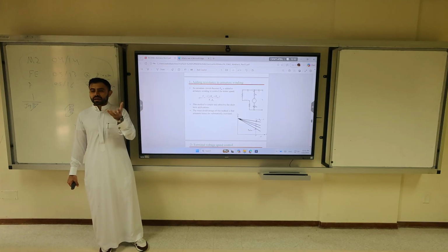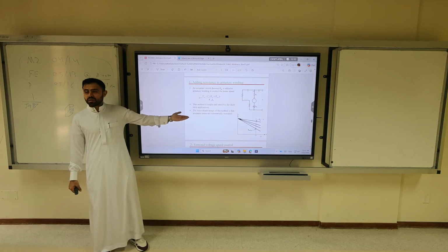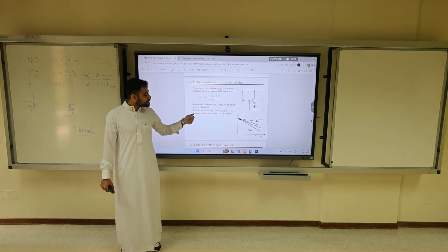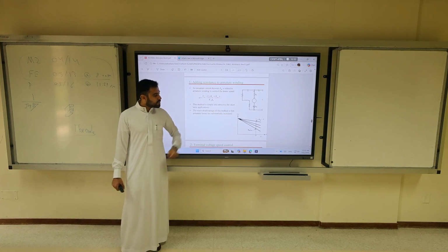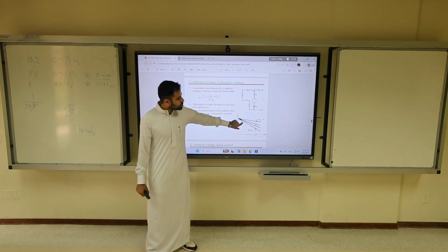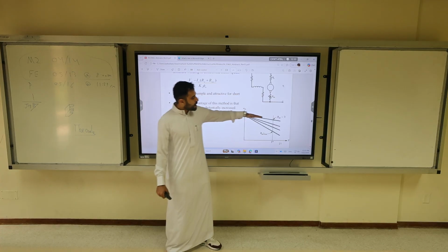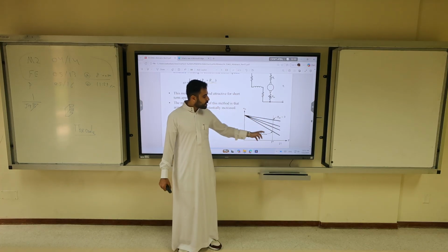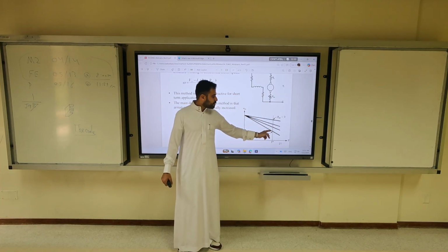What is the drawback? This is one of the questions that I like to ask in the exam. The main disadvantage of this method is armature losses are substantially increased. So this is the curve. RA at 0 is that. If you keep increasing it, you might reach a point where the speed is too low, and then the losses are very high.